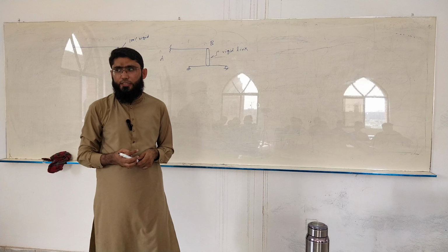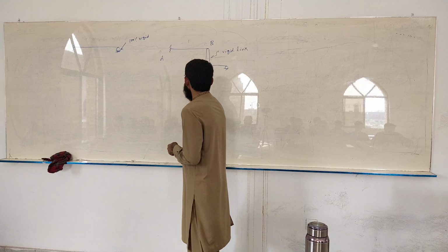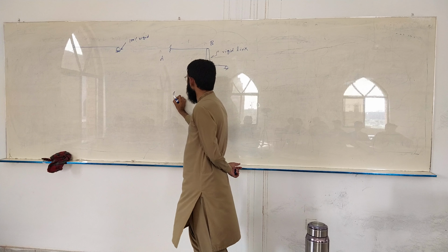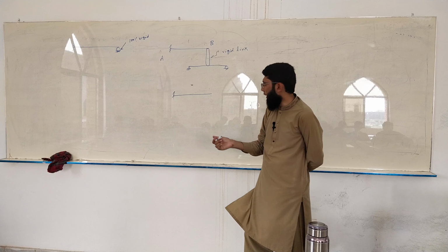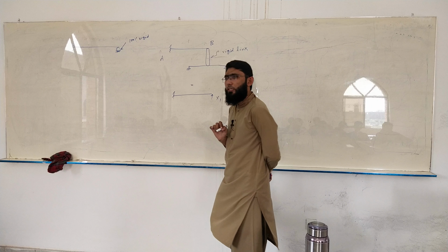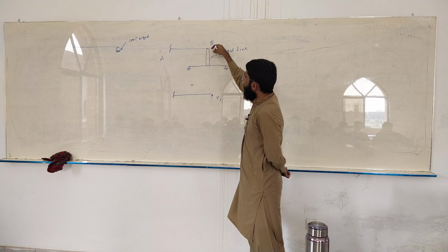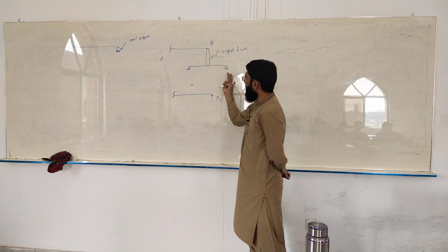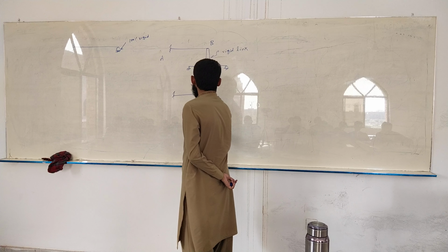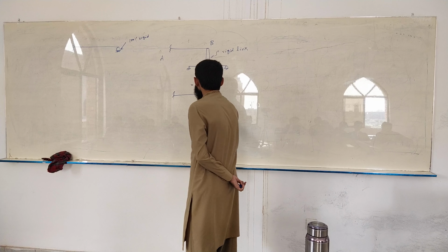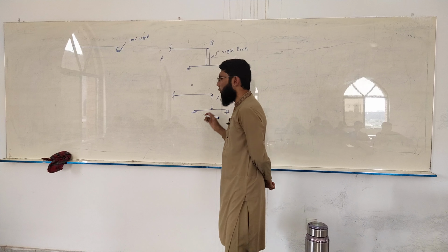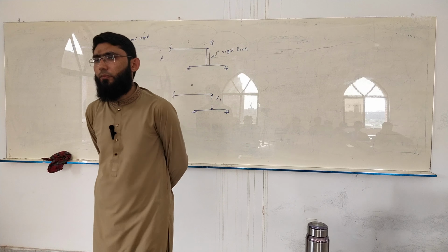The best approach that I understand is, well, what is the action of this rigid link on the beam? A force. Understand? This is x1. And what is the action of this beam on this beam? A force, and it is the same magnitude force, x1. This is Newton's third law. Simple enough, I think.